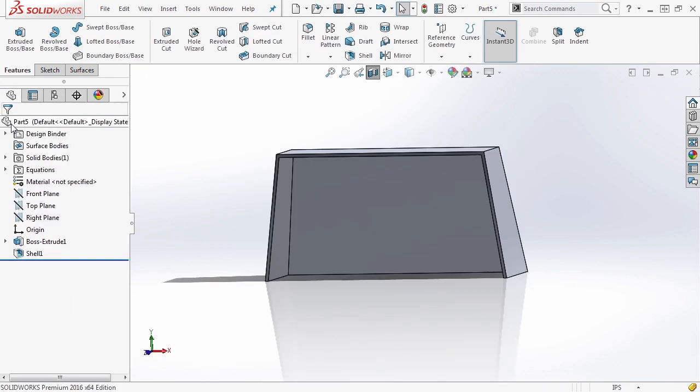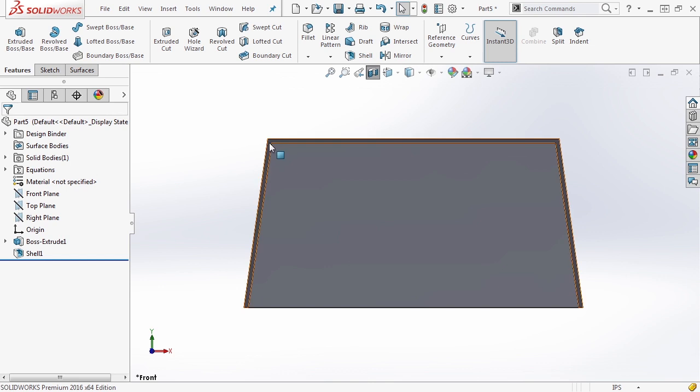If we do a section view using our front plane, you can see that the outside is going to be pulled from the top. So the mold will be pulled up as we're looking at it in the Y direction. And the inside will be pulled in the minus Y direction. And this is a typical orientation of a very simple drafted part.